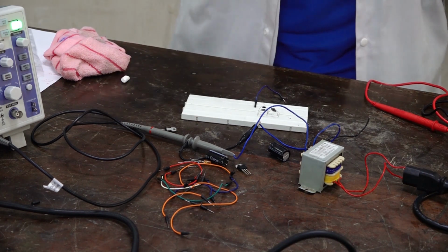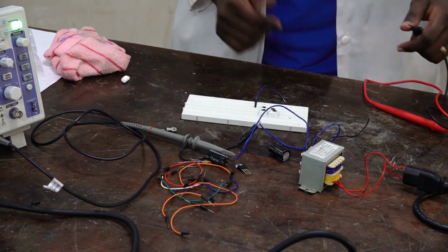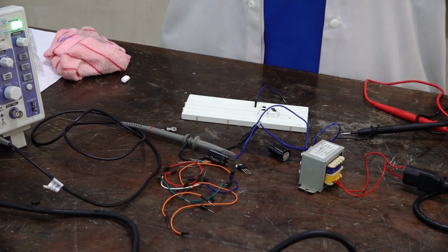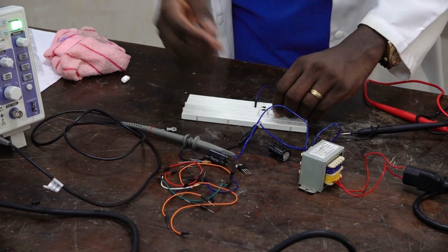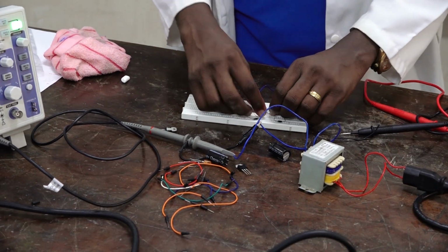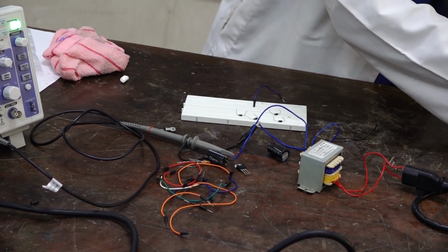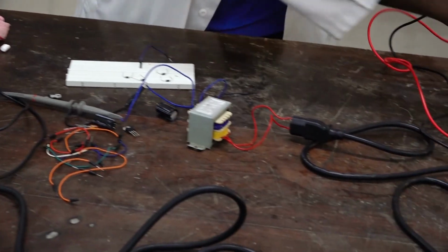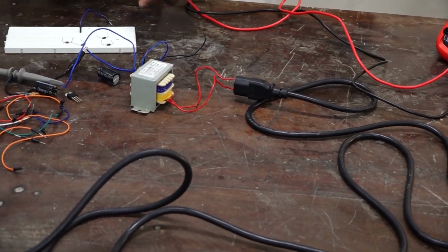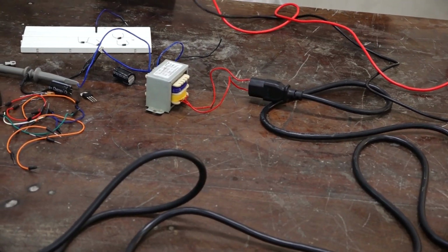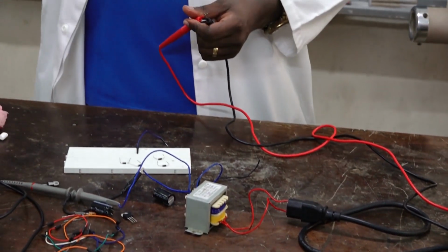Another thing which I did not tell you is that before you use your material, it's better to check if the diodes are live or they have already burnt. So you have to take a digital multimeter and set it to the diode tester. If you measure the potential barrier of 0.6 something, that diode is active.